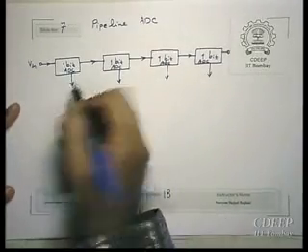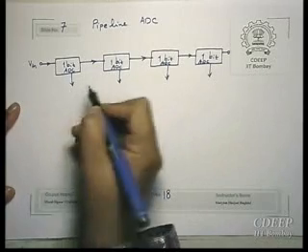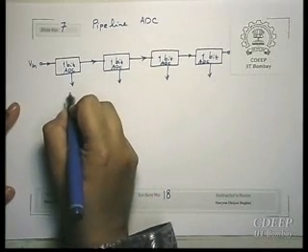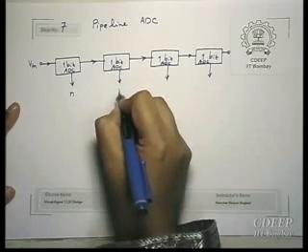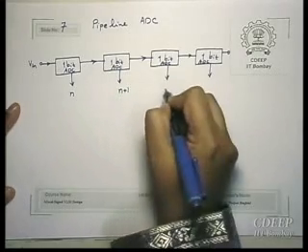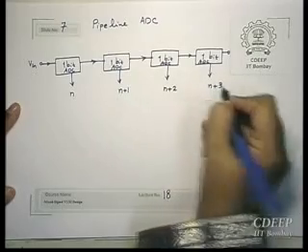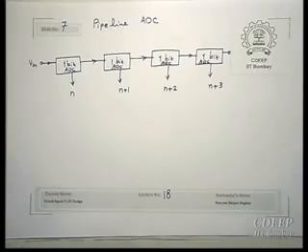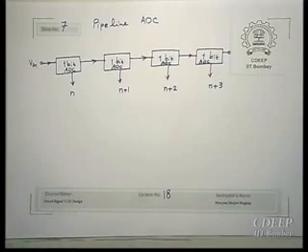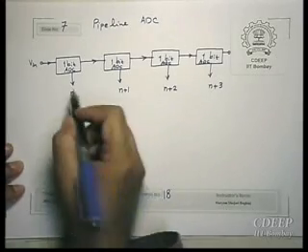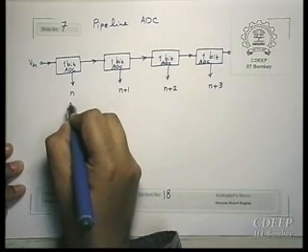So here now you have a clock cycle. For example, I called it cycle n. This is cycle n plus 1, this is cycle n plus 2, this is cycle n plus 3. So the conversion cycle may not be 1 clock cycle, it may be more than 1 clock cycle. But for example, this is the conversion cycle we are talking about. So first you will do 1 bit, so you will get the MSB.